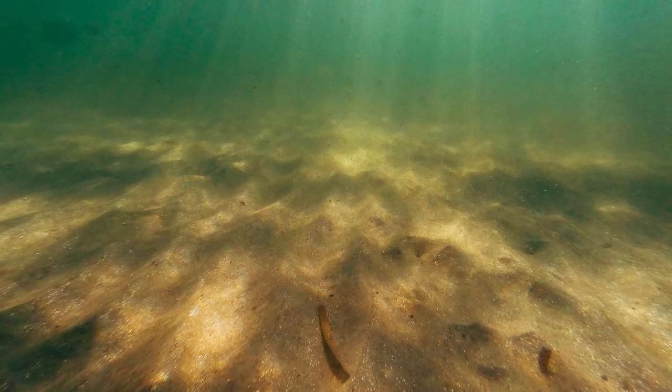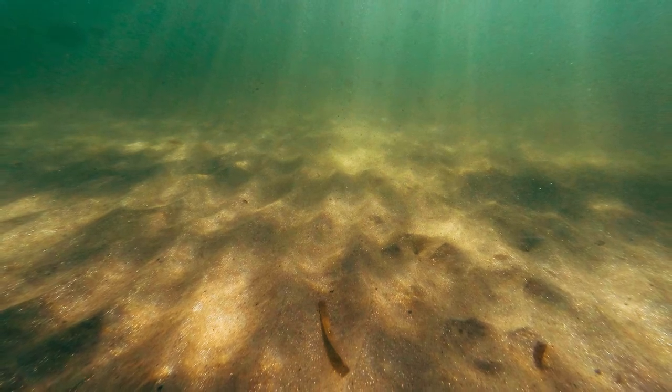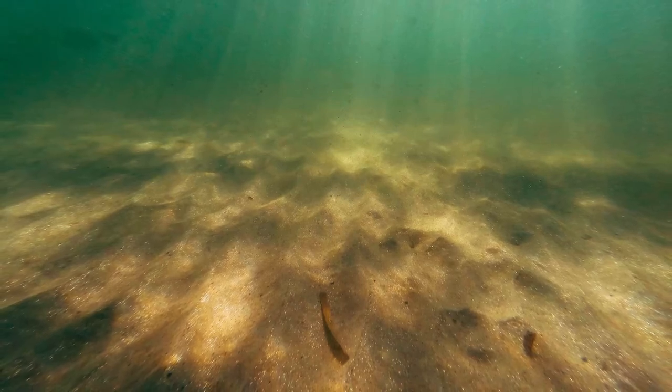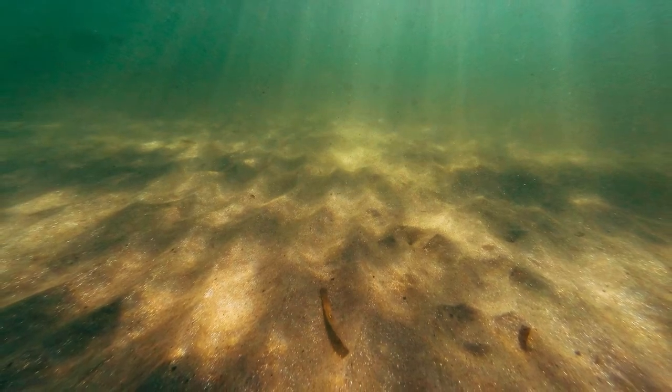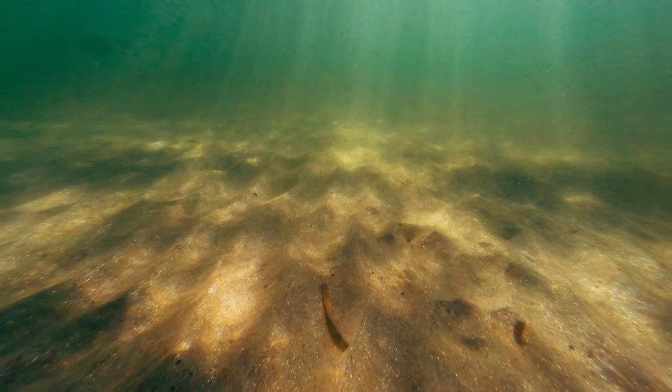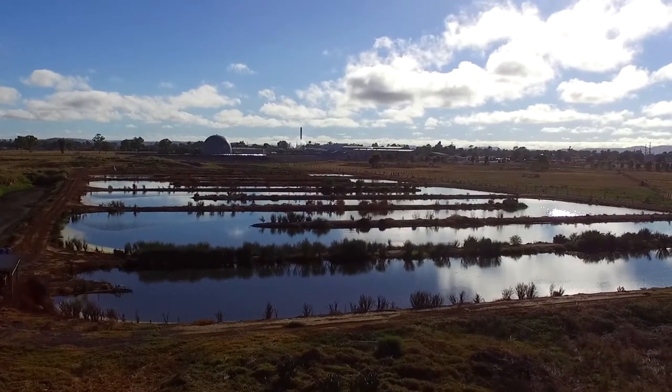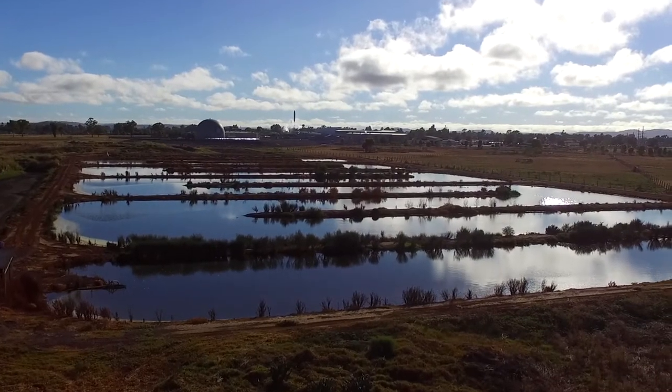The shallow ponds allow sunlight and oxygen penetration to the base of the pond. Often they are green with algal growth, which provides a rich dissolved oxygen concentration and have a high pH, which helps to kill pathogens. To achieve a good degree of disinfection, wastewater needs to be retained in the pond for 20 days or more.